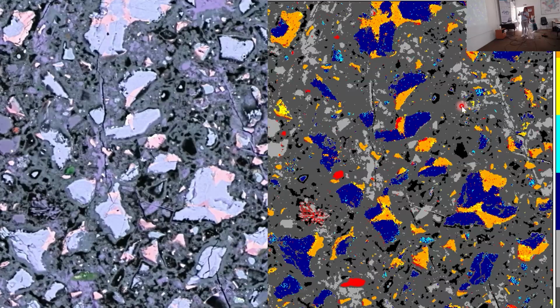So this is to give you an idea of what we speak about. This is a picture on the left of normal cement, the classic Portland cement. What you see as bright particles are the cement grains, and they are made mostly of two types of components, which are bluish or reddish. So the cement, when you mix it with water, will dissolve and produce the hydrates, which are in gray, and purple, which are the glues. So this glue is why our buildings are standing. And you have in black the porosity.